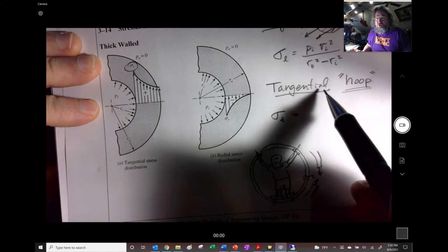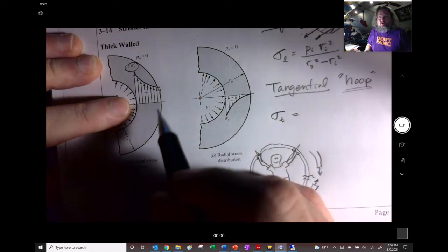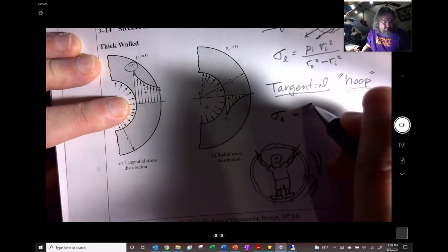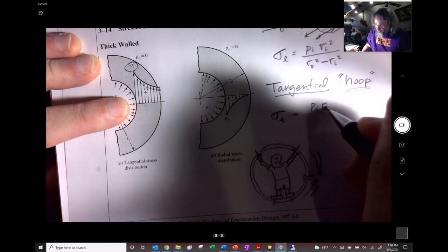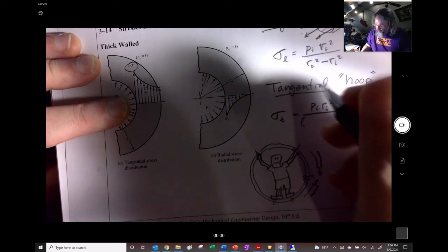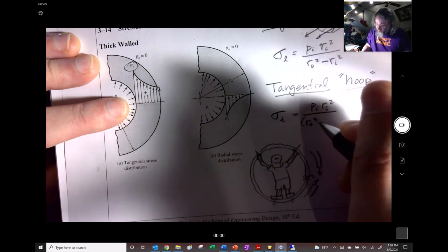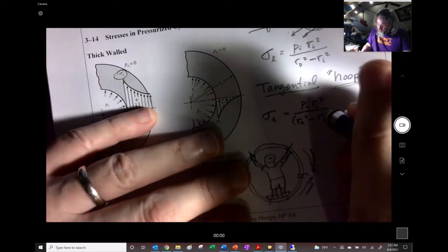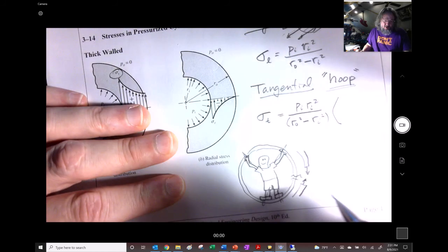And it's tangential, right? It's tangential surface. So it really is coming in this direction right here. So the equation for the hoop stress, let me get this right. I think I swapped the P and the R, but that didn't matter right there. You'll see it's almost identical to the radial and the longitudinal in this first part over here. So we have the RO minus RI. Oh, that's got to be squared. Both of them have to be squared. Make sure you don't put the square on the outside there. There you go.